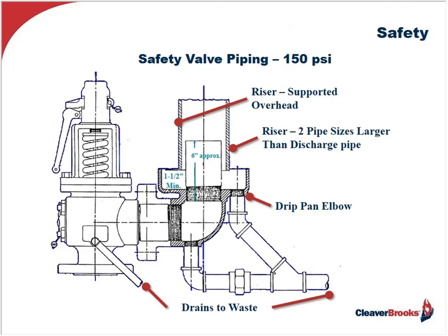Those safety valves should be piped independently with adequately sized vent riser piping, which is free-floating and properly secured and supported at the roof. Anything less, and we're asking for trouble.